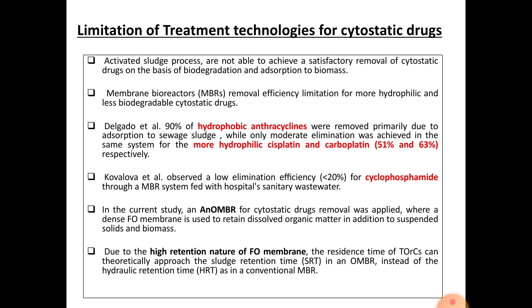But the membrane bioreactor technology and its removal efficiency have some limitations because of the hydrophilic nature of the cytostatic drugs. As can be seen, some of the authors reported 90% removal of hydrophobic anthracyclines due to adsorption, while only a moderate elimination was achieved for hydrophilic cisplatin and carboplatin.